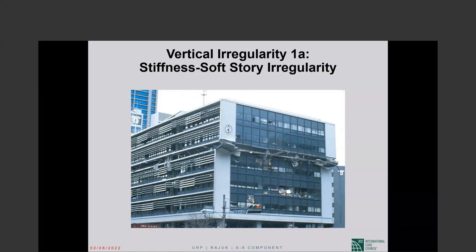Anyway, as you go up the building, like shear walls are discontinued quite often. You don't need what you need in the lower portions of the building. Your structure can be less stiff. And so they discontinued the structural steel shapes. From steel reinforced concrete, they went to all reinforced concrete. And in the city hall, that happened. So the steel shapes were discontinued here.